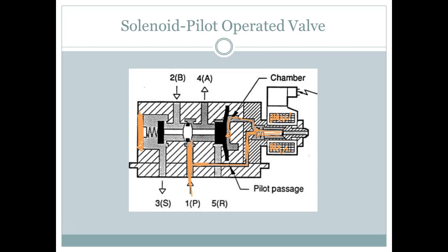Are we okay? If we were over at the amateur line, you can see the valve bodies are exactly the same, but they'll have a solenoid on one side, and on the other side, it'll have an Allen wrench going in, and what's in there? Well, it's a spring. So what they've done is added that solenoid with a spring return. And you'll see solenoids on both sides, but the valve bodies themselves look what? They look identical. And it only makes sense.